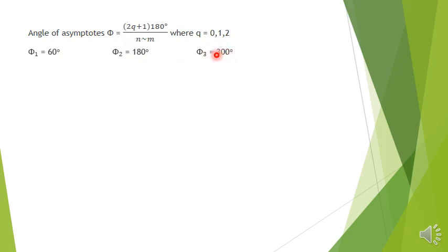Okay. Next point is the centroid, where these three asymptotes intersect on the real axis. So centroid sigma is equal to, as per the formula, summation of poles minus summation of zeros divided by n difference m. What are the open loop poles? 0, minus 2, minus 4. What about open loop zeros? No open loop zeros, so 0. Divided by n difference m. So minus 6 by 3, that is minus 2.